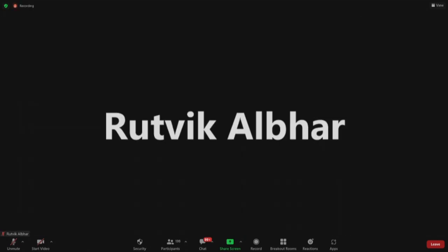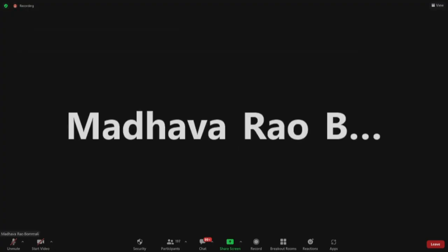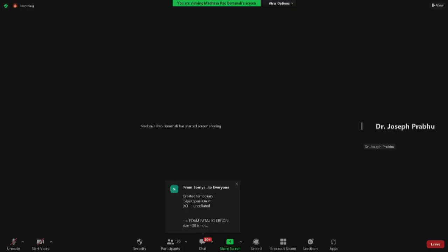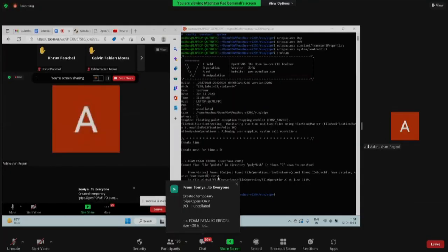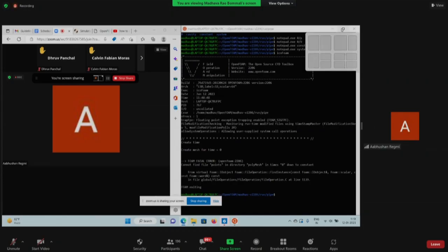Hello, sir. Who is this? Sir, this is Madhav. Yes, Madhav. Sir, it is showing cannot find file points in directory volume. Can I share my screen? Actually, we need to run blockMesh and icoFoam, right? Yes, you're right. Sir, can you see my screen? Yes, Madhav. Here, it is showing cannot find the file points in directory. I think you have not done blockMesh, so you need to do blockMesh.